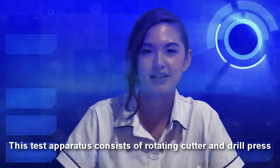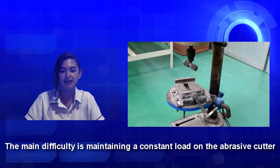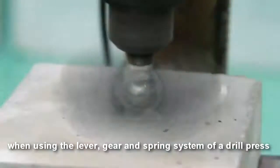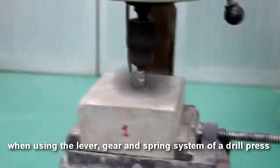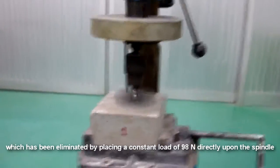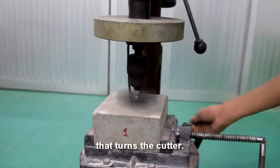This test apparatus consists of rotating cutter and drill press. The main difficulty is maintaining a constant load on the abrasive cutter when using the lever, gear, and spring system of a drill press, which has been eliminated by placing a constant load of 98 newtons directly upon the spindle that turns the cutter.